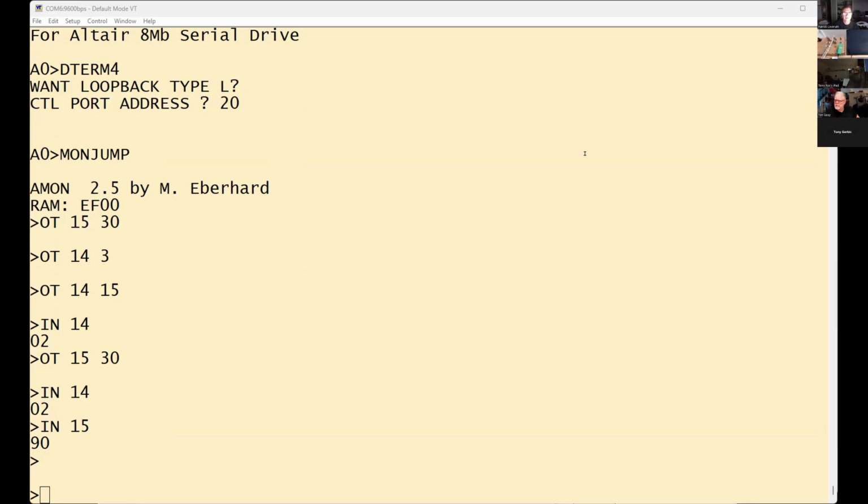So it either isn't transmitting or, wait, is pin 1 on the left or the right? From the left side, it's the second and third pins. And those 2 switches are on the port. What 2 switches? Switch 1, that has the DCD and CTS. They're all on. Like I say, that setup on the Altair 8800C, everything works.